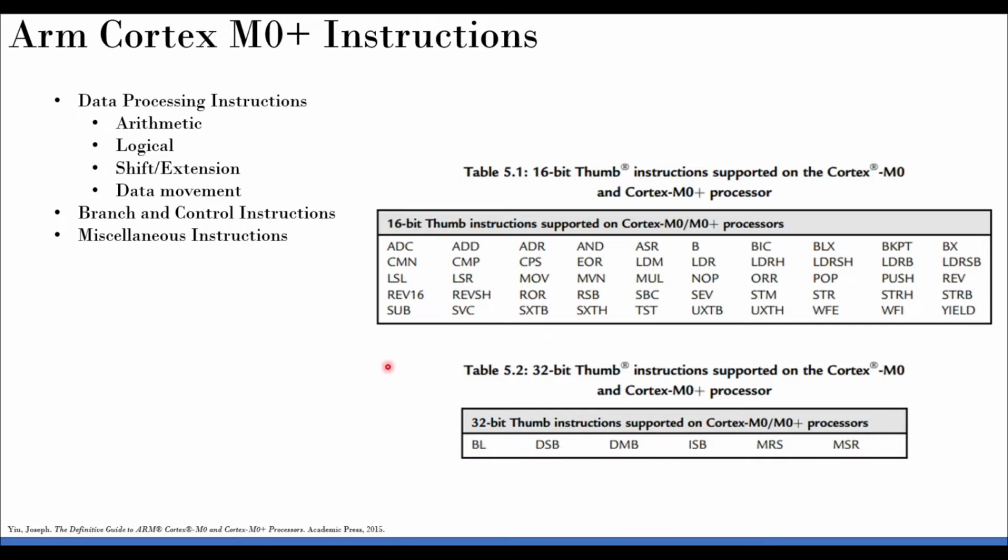Even here, we may not be using all the commands. Interesting to note, there's BL here, and at the same time there's a branch B and BLX, BX. All these are branch statements, but they are 16-bit, compared to this one, where no operand is given; it's just the mnemonic alone that occupies 32 bits for a specific purpose. We'll learn that as we go along.